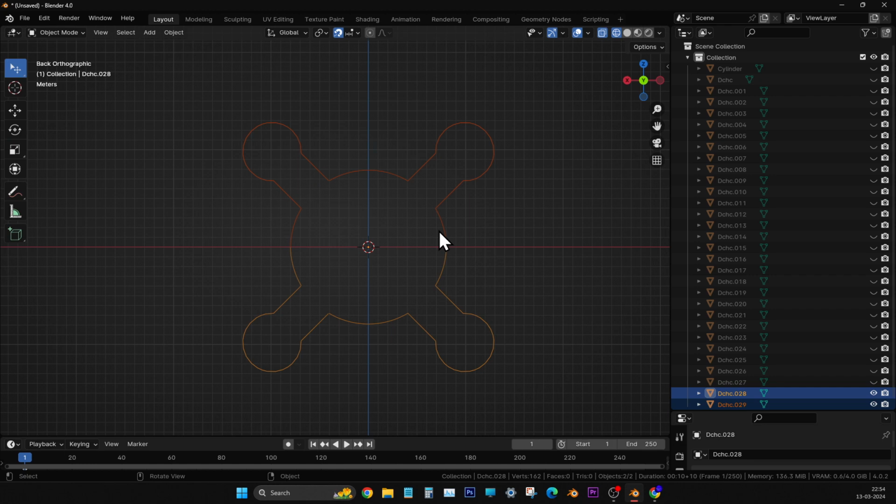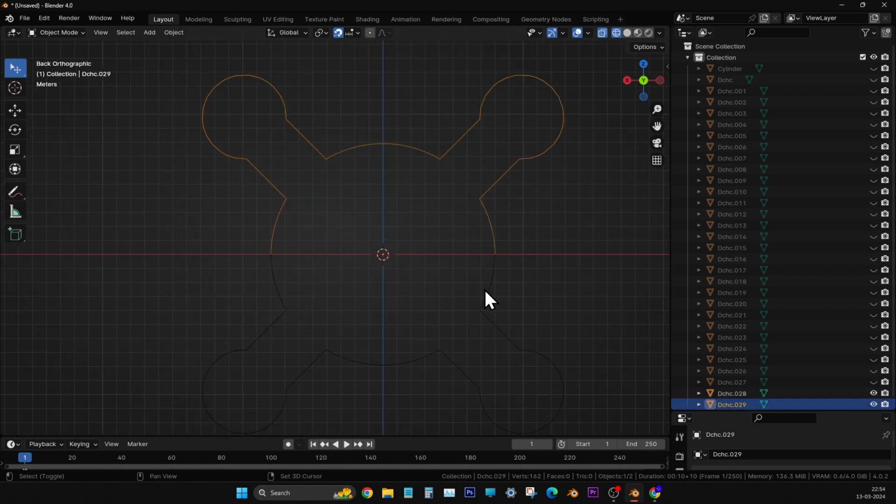Here in Blender context, merging means it is about components, that is vertex to vertex, geometrical merging. When it is joining, it means objects, both objects are becoming one object. So merging means both vertices, components, are becoming one single component. Now we are going to join it.